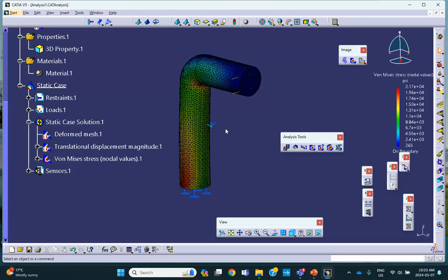Okay, but keep in mind that the yield strength that I used here for steel was 30,000. If this is a high strength steel, for example, that they use in submarines and ships and things like that, the yield strength is a lot higher. It could be as high as 100,000. Then some of these would have been okay.